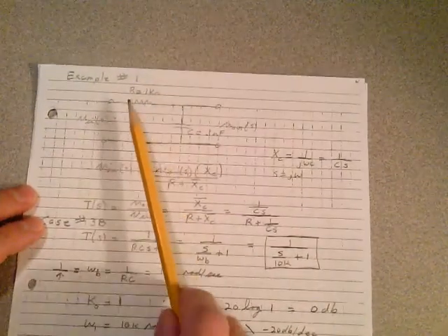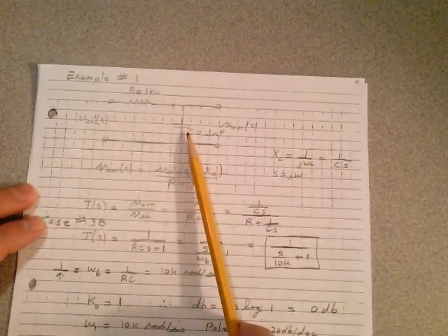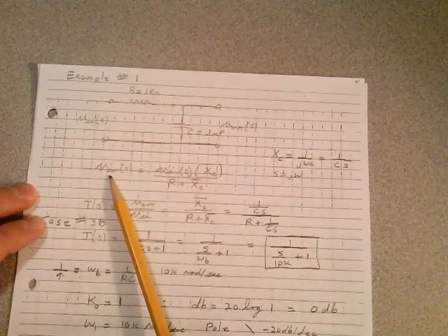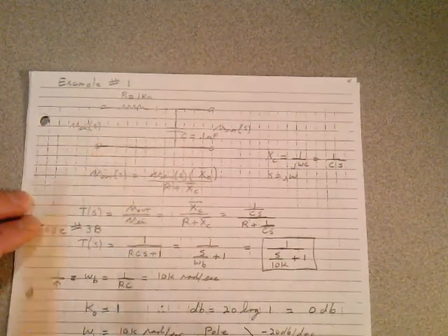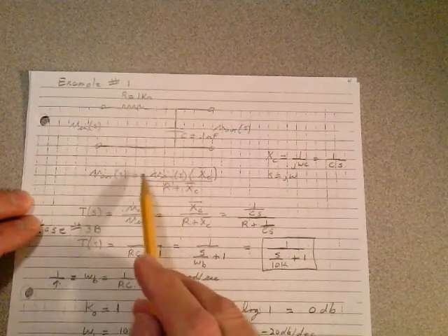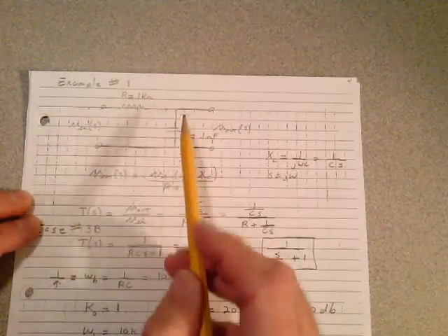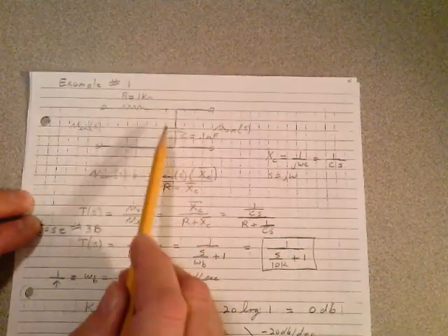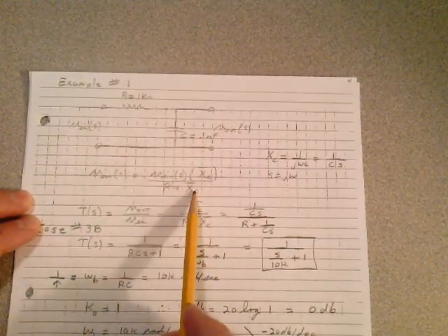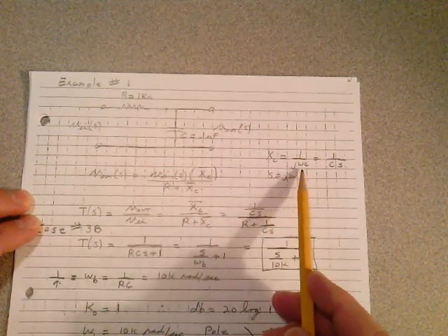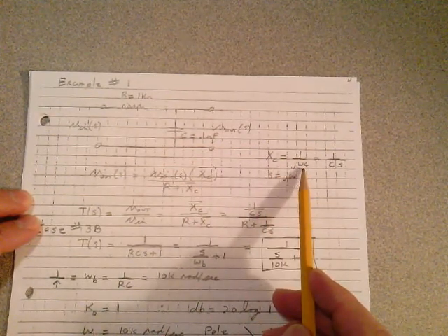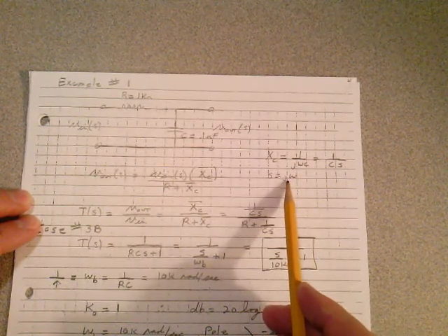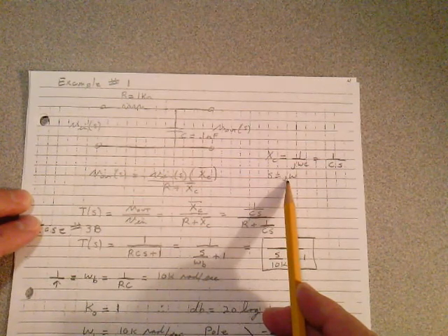Starting out on page number 195, I want you to take a look at our first example. It's a simple RC circuit. And what we're going to calculate here is the output voltage based on the input voltage, and everything's in terms of S. So V out of S is equal to, by the voltage divider rule, V in of S times the reactance here, divided by the sum of the resistance and the reactance. We know that the reactance is 1 over j omega c, and we're going to let S equal j omega as a complex variable. That's all this does, is just let S equal j omega to simplify the appearance of these transfer functions right now.